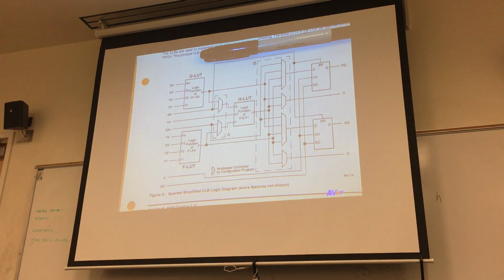You should really ignore the number of gates because it doesn't tell you anything. Again, what can you implement with 10,000 2-input NAND gates? I have no idea. It was just a figure of merit to give you an idea that if this FPGA has 5,000 gate equivalents and this one has 10,000, then I should be able to do twice as much with the latter one. But that still doesn't tell me how complex a circuit you can build.